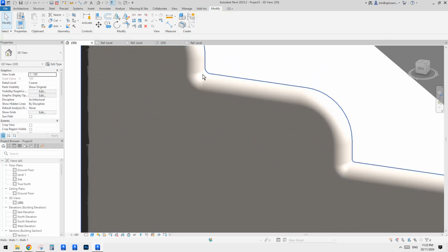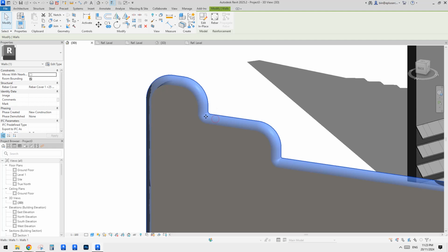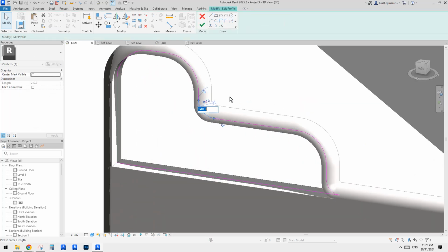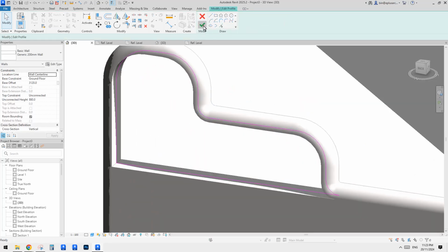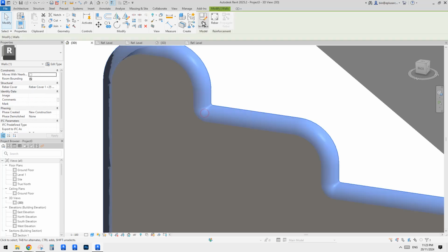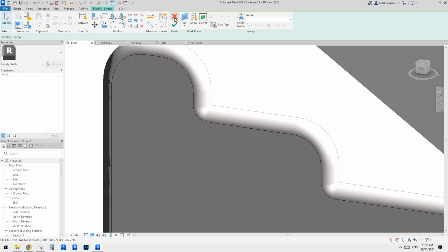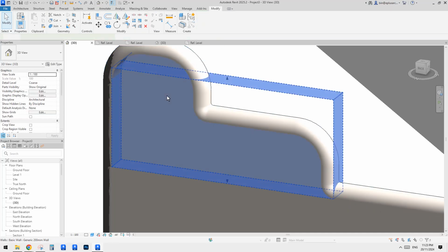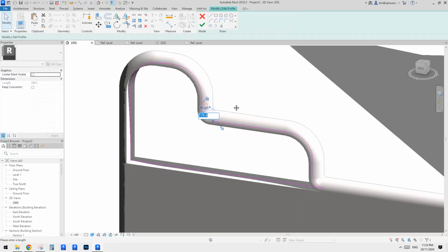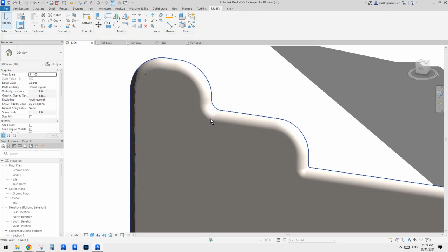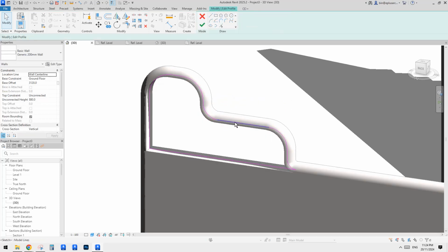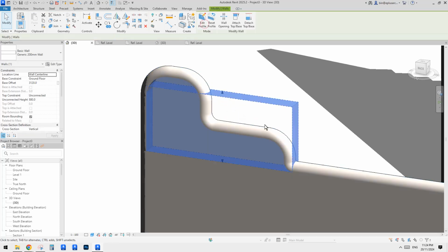And also you can see here, currently the radius is quite small. If it's smaller than a certain number, it will break. Okay, so just be careful. Yeah, just make sure. Sorry, we don't need to go into the modeling. We do it in the wall, not in the model in place, because that sweep will automatically match this wall, right? So see, if you change this one, yeah, all good.